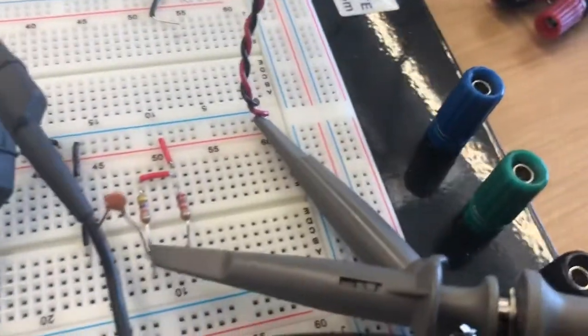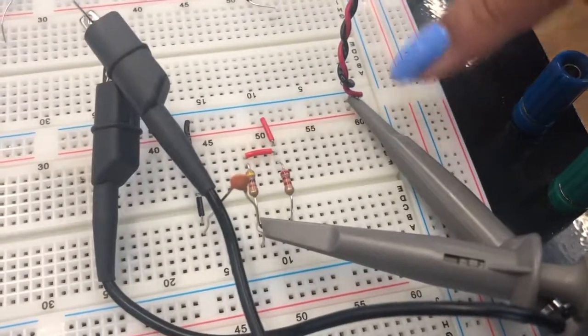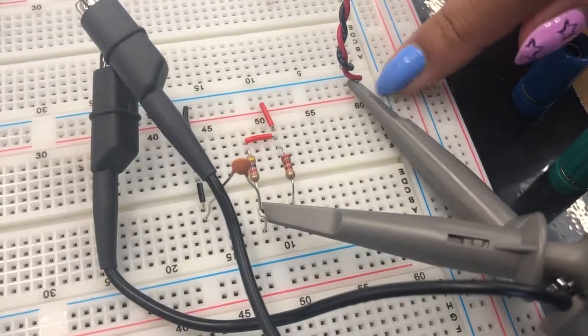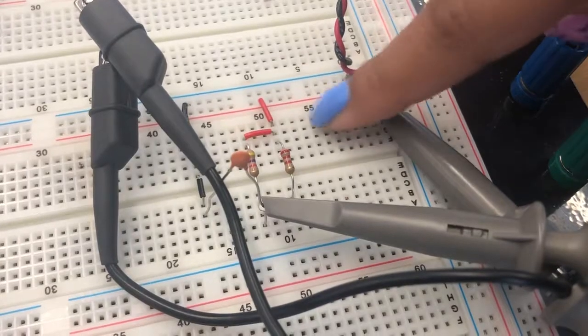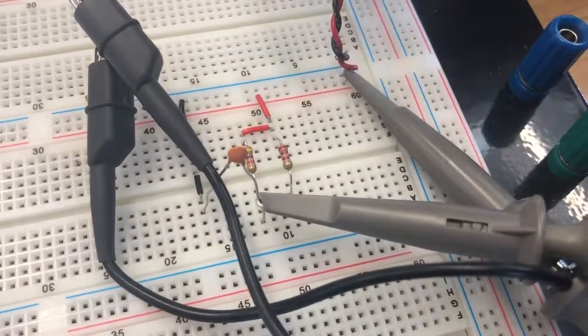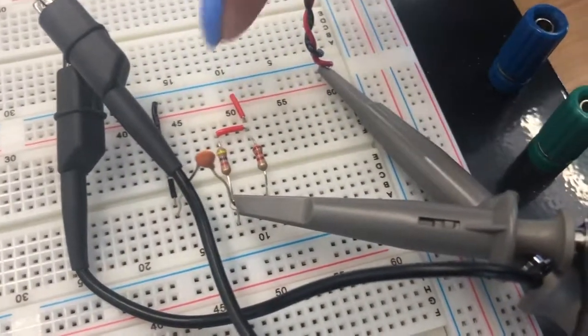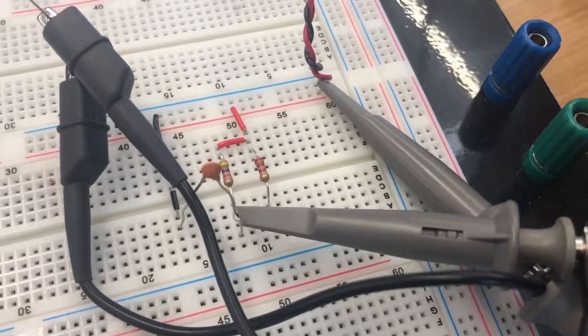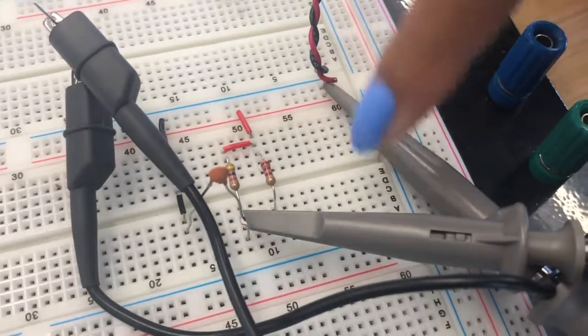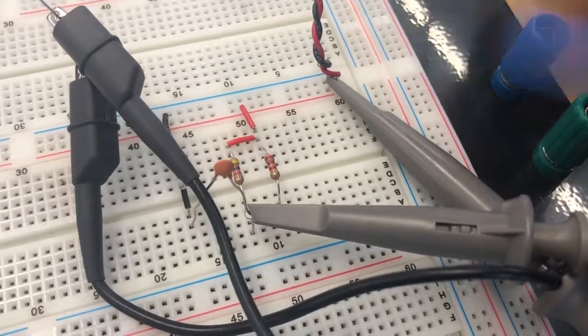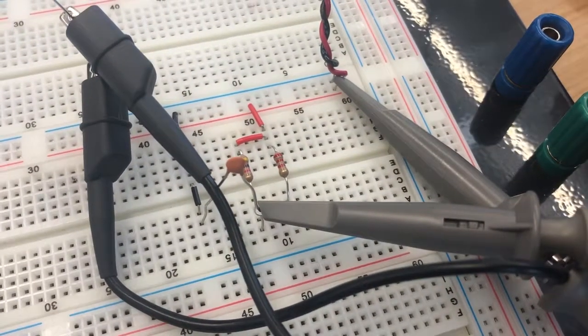And this is our low pass filter circuit. So here we have the input, connected to channel 1 of our digital. This connects to the resistors, which are in parallel, and to combine, they form an equivalent resistance of 1.5 kiloohms. Then that connects to the capacitor, which has a value of 0.001 microfarads.